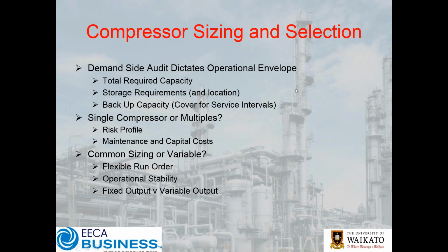Now, just a quick point on compressor sizing and selection. Once you've sorted out your demand side, looking at your leaks and your artificial demand, inappropriate use, etc., you'll have a good idea of what your actual requirements are, what your storage requirements are, remembering the location of that storage might not be all in the plant room, what backup capacity you need, and just at this point, remember that if you're running around the clock, you need to allow to be able to service your equipment and have additional machines to be able to have one off to be serviced or taken out, redundancy.